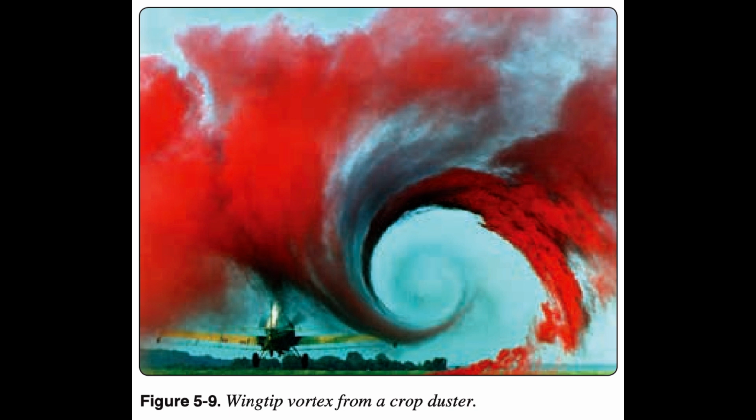In level flight, the aerodynamic properties of a wing or rotor produce a required lift, but this can be obtained only at the expense of a certain penalty. The name given to this penalty is induced drag. Induced drag is inherent whenever an airfoil is producing lift and, in fact, this type of drag is inseparable from the production of lift. Consequently, it is always present if lift is produced. An airfoil, wing or rotor blade, produces the lift force by making use of the energy of the free airstream.